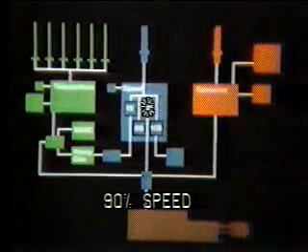The engine continues to increase its speed as the fuel is increased in proportion to the maximum acceleration schedule. When the engine speed reaches 90%, gate number 3 on the speed monitor closes. Relay K263-1 is energized and transfers contacts. The transfer of K263-1's contacts transfers the control of the servo actuator from the main fuel actuator to the governor.